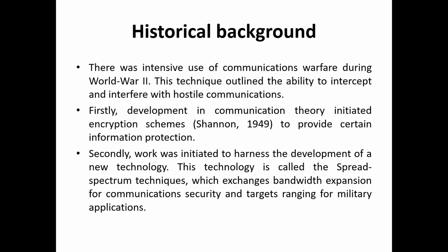This technique outlined the ability to intercept and interfere with hostile communication. Okay, hostile means al-muadi. Firstly, development in communication theory initiated encryption schemes by the Shannon law formula, as you know, in 1949. I think you are familiar with the Shannon law formula, which is what? C equals B log2(1 + SNR). Of course, log base 2, and C represents the bit rate of the channel, and B will be the bandwidth of the channel. So the bit rate relates to the bandwidth and the signal to noise ratio.